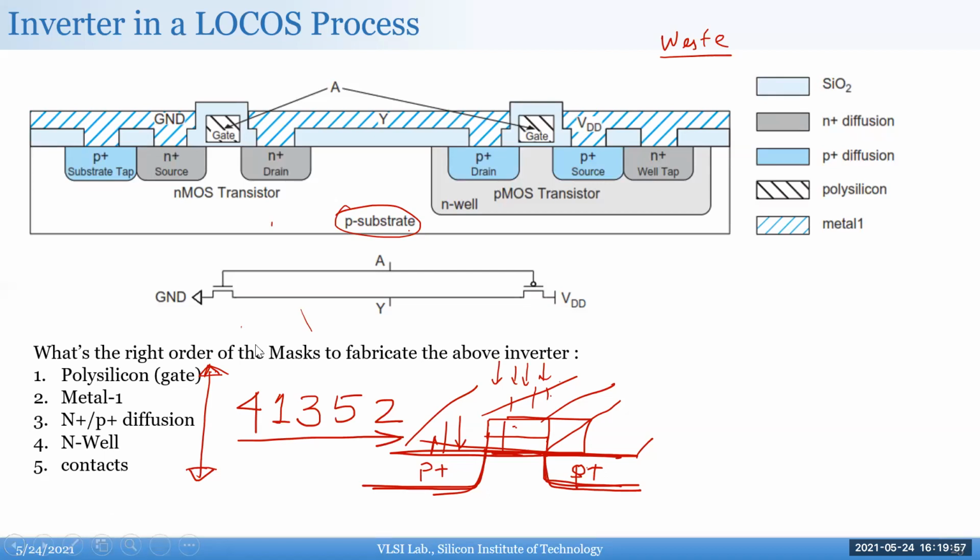Like I said, you have the combinations of making the photoresist negative or positive, the mask positive or negative. So you can etch them in any fashion you want, but whatever you choose, you draw the layout accordingly. If you say, I want to do positive mask, positive photoresist, and I want the metal and oxide to be there where the figures are drawn, then you choose the appropriate thing. But whatever you choose, you just stick to it, and then show the process. Okay, so I think everyone is clear so far.